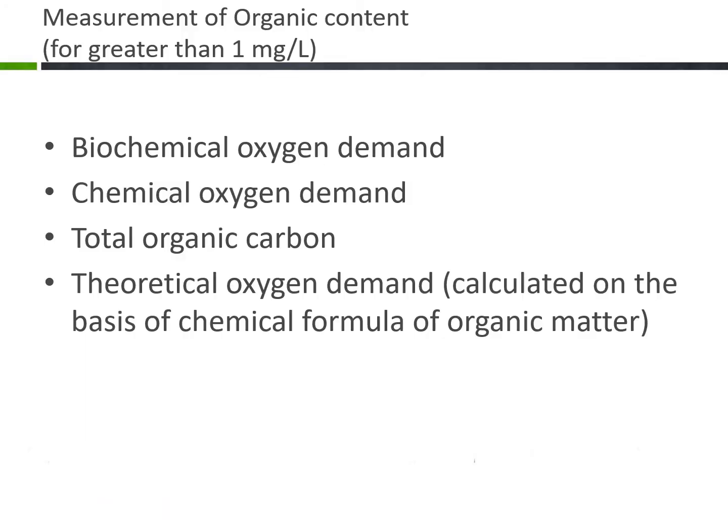So, for measurement of organic content, we need organic content measurement methods: the biochemical oxygen demand (BOD) test, the COD test, and the theoretical oxygen demand, which is calculated on the basis of the chemical formula of organic matter. These are the methods and calculations which help us in determining the total amount of organic content present in the wastewater.